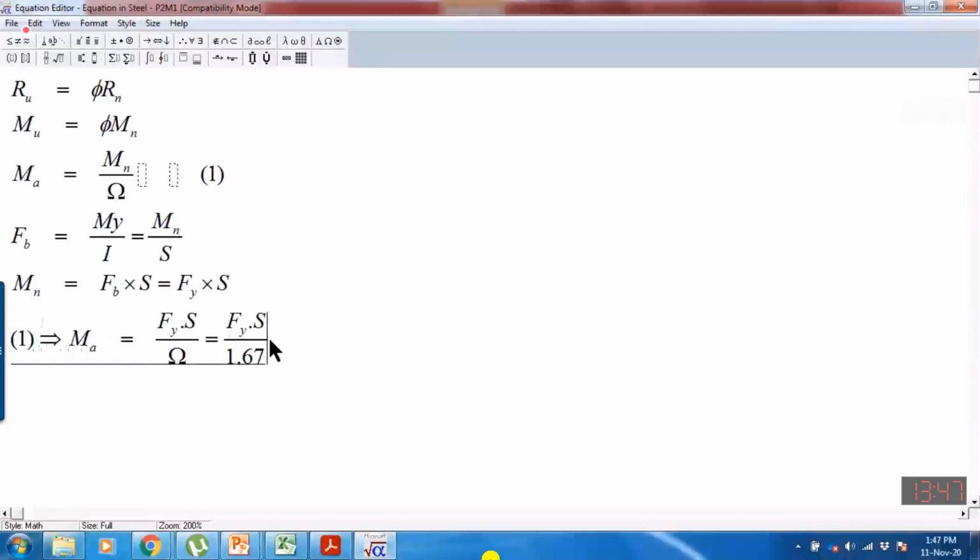This thing we will study in detail in our beam design topic. In the beam design topic, we will say that if a beam is not appropriately braced in the lateral direction, lateral meaning horizontal, not the vertical downward direction, then it can fail at a load value less than that based on Sx.